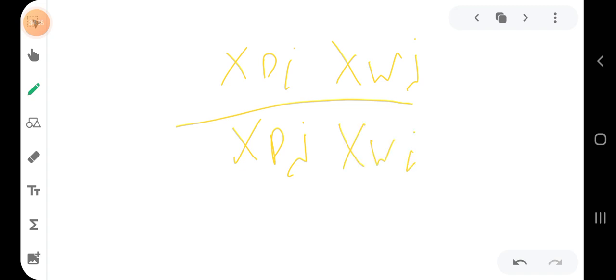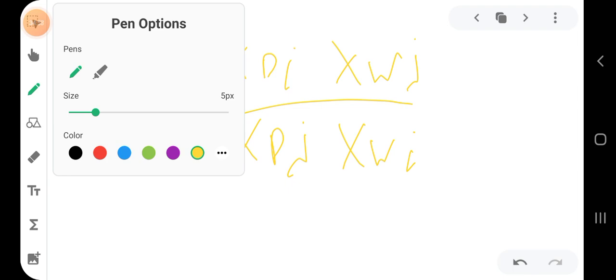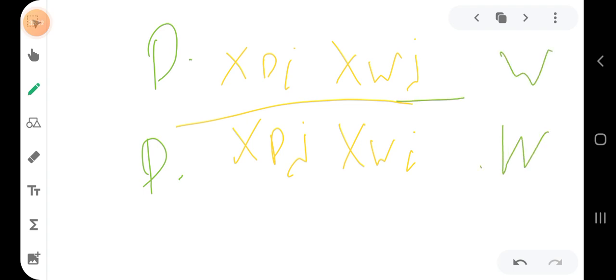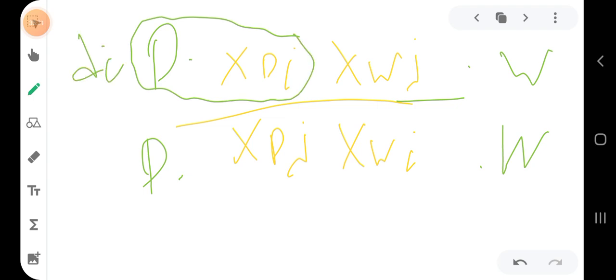So a good point to notice here is that if you multiply both the numerator and denominator by the distillate, and if you multiply again both numerator and denominator by the waste, what you get is that, what's this? D times x Di. It is just Di, which is the flow rate of the component I, light key, in the distillate.